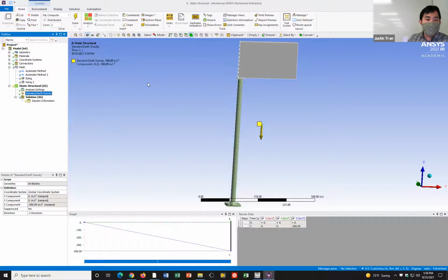Does it account for both FZ1 and WZ1? Yes, both of them are included in this. If you look back at the project specs, you can see that I actually have separate forces there that have the weights, but this is going to take care of both. The question is, for the default steel, do we need to add the density? No. Steel is fully specified, so it has its density, its Young's modulus and Poisson's ratio. It actually has a bunch of other properties too, but it definitely has density.